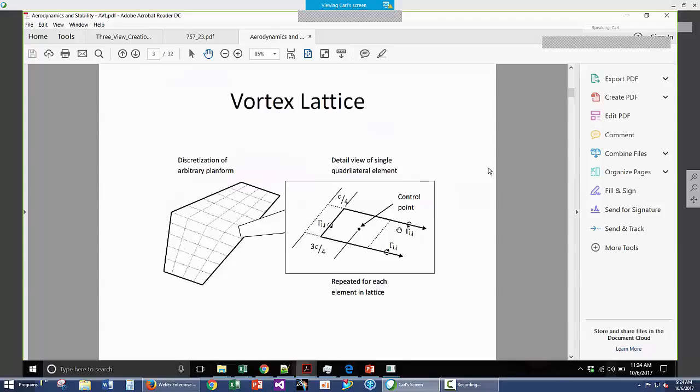So depending on what our camber distribution or camber line looks like, we can define a normal to the camber surface, and the velocity normal to the camber surface should be 0, right? Based on the induced velocity due to every single little horseshoe vortex that we have on however many lifting surfaces we have, in addition to the free stream flight condition. So that's what's happening in the background. You don't necessarily need to know that, but there are particular limitations.